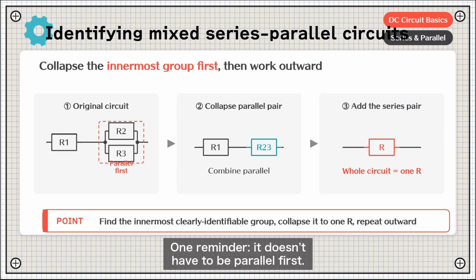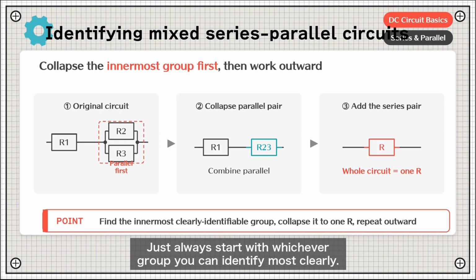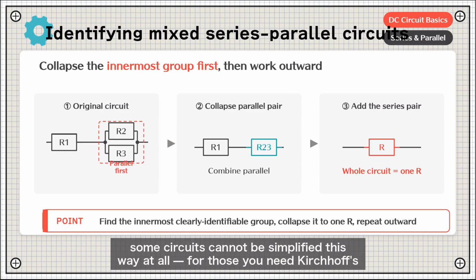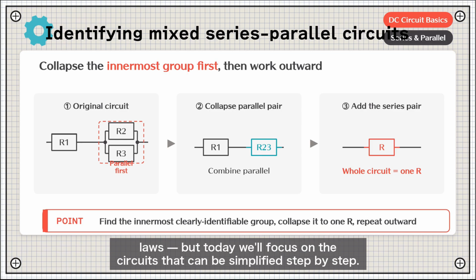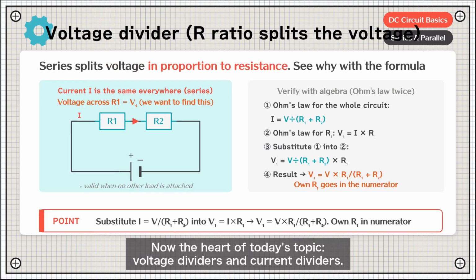One reminder: it doesn't have to be parallel first. Some circuits have a series group on the inside. Just always start with whichever group you can identify most clearly. Also note, some circuits cannot be simplified this way at all. For those you need Kirchhoff's laws, but today we'll focus on the circuits that can be simplified step by step. Now the heart of today's topic: voltage dividers and current dividers.